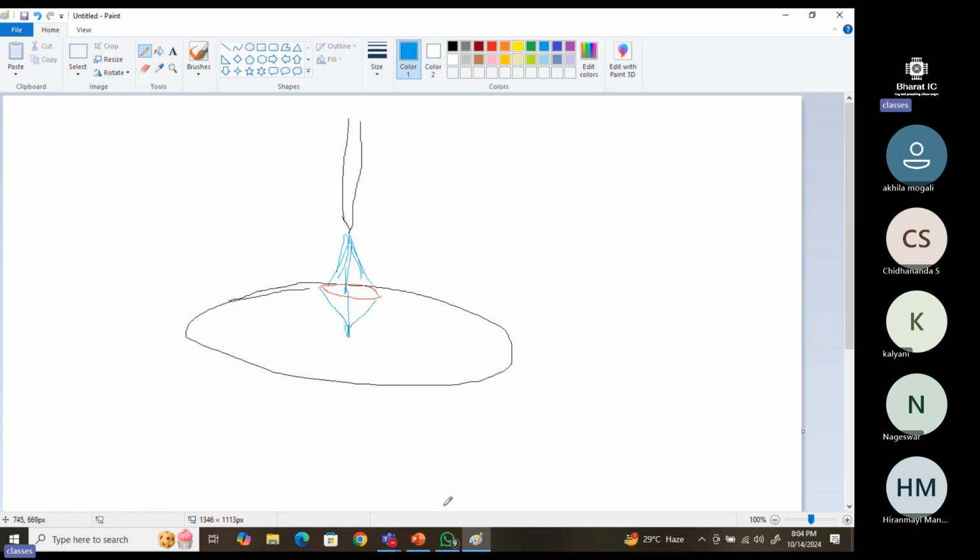Now, if you see here, the angle of incidence matters, what quality of ion is generated from what kind of source. The target material matters: what wafer, how the doping is, what the quality of the wafer is. The ion beam quality matters, and the angle of incidence matters. These three factors matter.